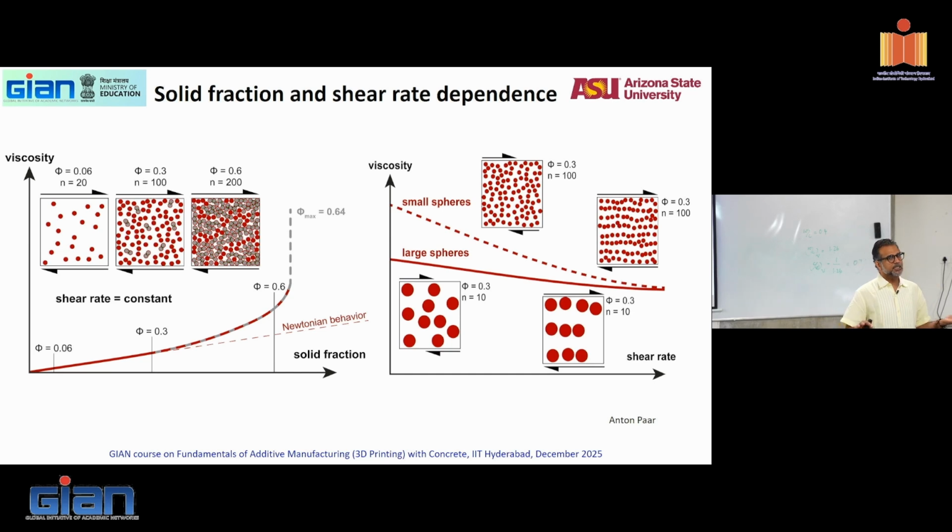So viscosities depend on, again, just to show you the influence of size and volume fraction, both these two things. Shape, even though cement particle shape is very important in all simulations, because we are all lazy, we'll assume all cement particles to be spherical and move on. It really doesn't make that much of a difference in your calculations, but it is the volume fraction and the size that matters. Okay, and those are shown in this picture.